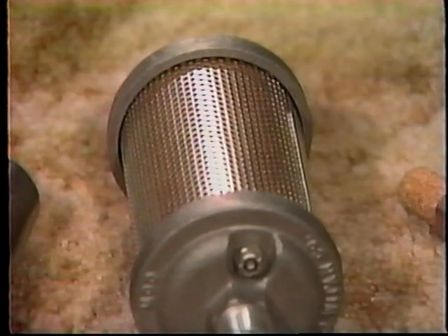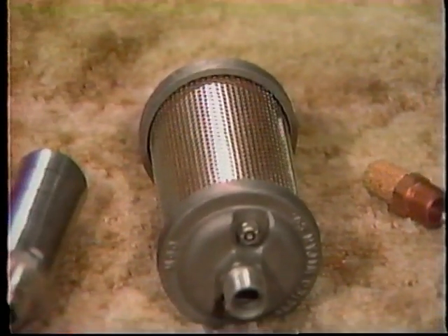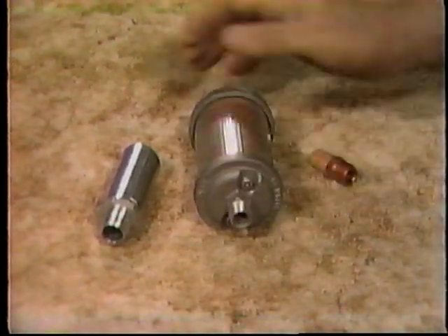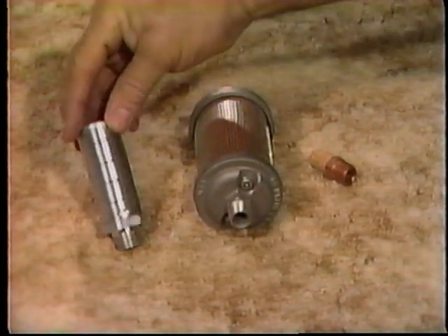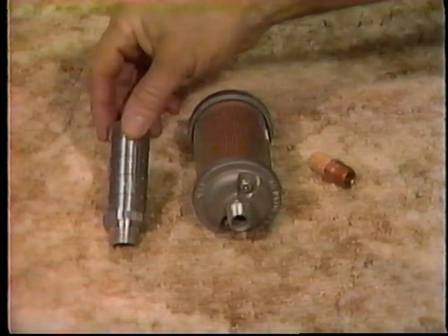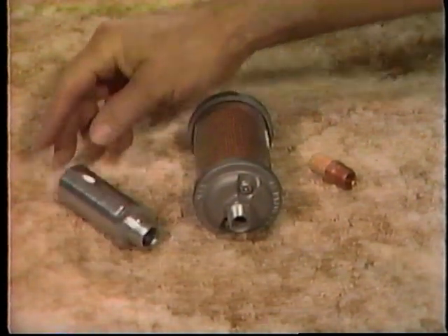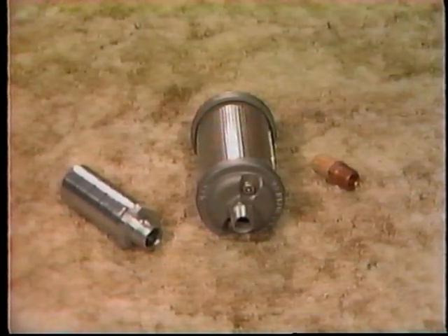In many pneumatic systems, unmuffled, exhausting air can generate quite a high level of noise. Over long periods of time, this may cause loss of hearing and operator fatigue. So to reduce this noise, the system may be equipped with a silencer, or muffler as they're often called. And there are several types of silencer designs used today. Energy of air exhausting from the system is diffused and the noise is reduced.